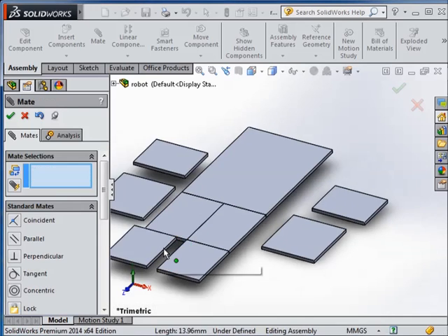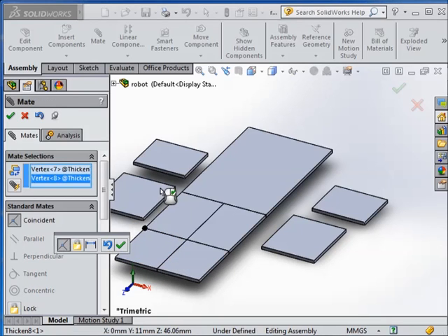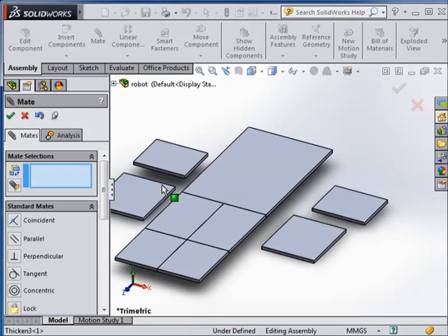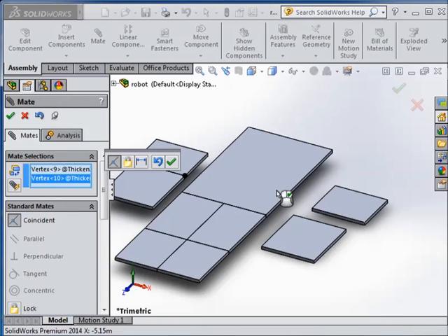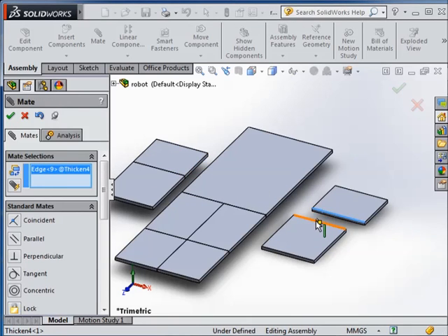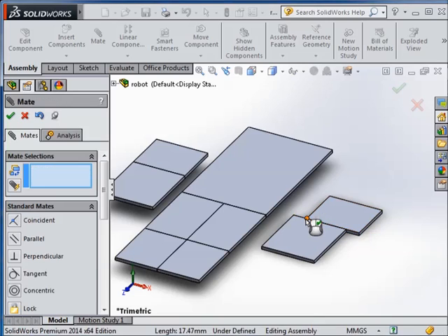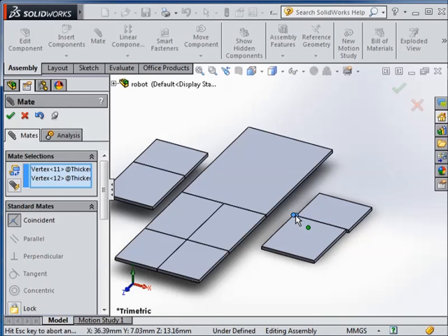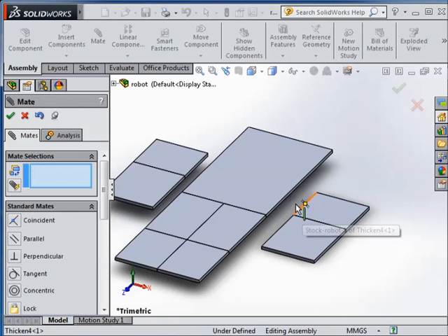But you need to do two constraints. One is an edge constraint, which defines the axis of rotation, and another is a point constraint between two points on neighboring bodies, which defines the translation along that rotational axis. Once you've defined those two things, you've pretty much defined how a hinge works in such laminate devices.